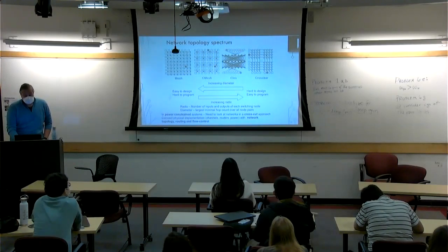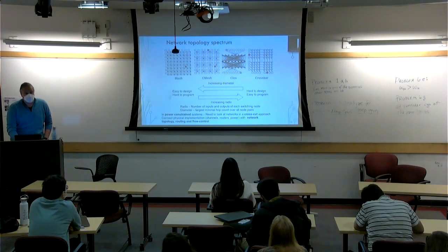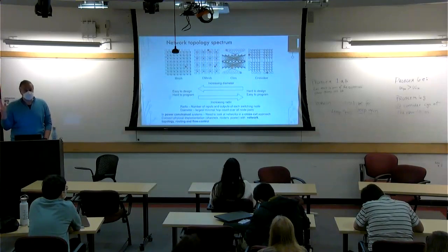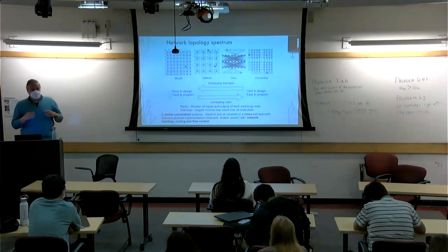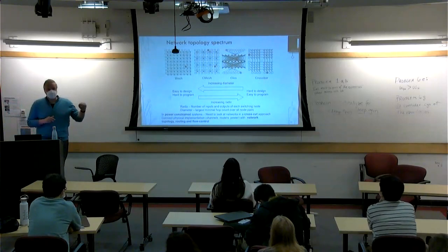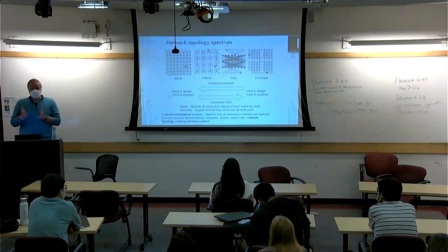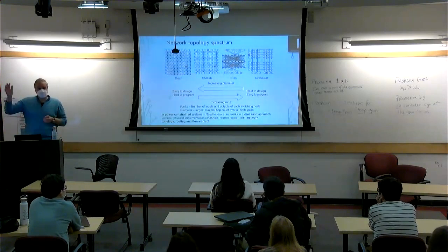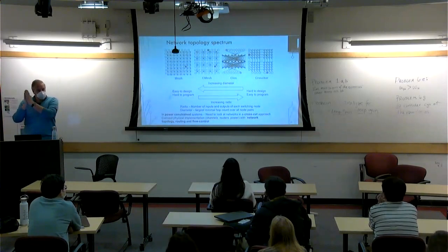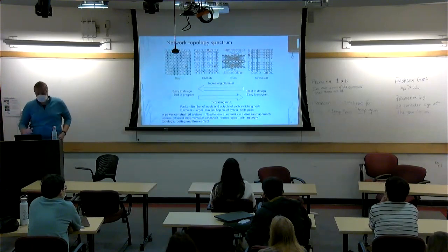And then we'll go through some other techniques. You can take that to much more complex networks like Clos that have multi-stage routing and allow you to do all sorts of things to even out the impact of different traffic patterns, which is very important when you're designing something to be good for all workloads. You don't want to design something that's only good for one application, then the application changes, and it all falls apart. You want to design something that for many different patterns and applications provides uniform, consistent throughput throughout the network.